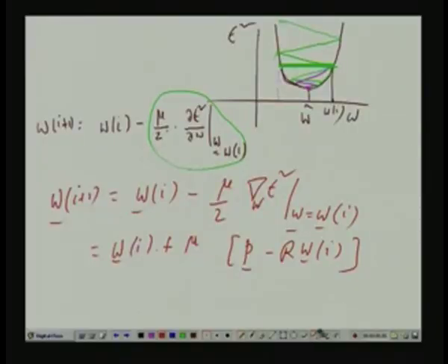For one set of R and P, you have got one Wiener filter. After some time, if that R and P changes, you get another Wiener filter. So, that means you have to adapt yourself by just looking into the data, and generate the corresponding Wiener filter by some adaptive method. Next time when the input statistics changes or P vector changes, you again adapt yourself and approach the corresponding Wiener filter, so on and so forth. If you want to do such a thing, I propose this.